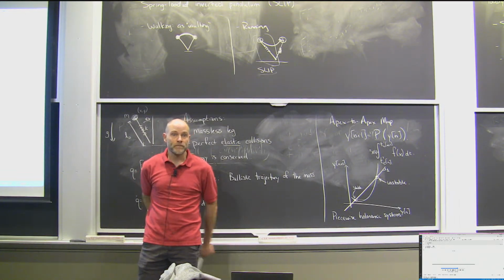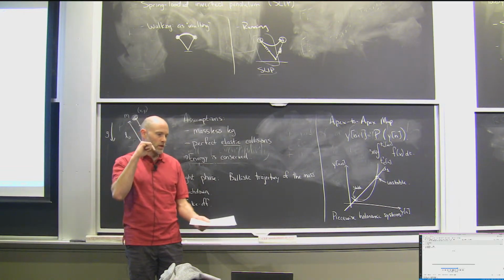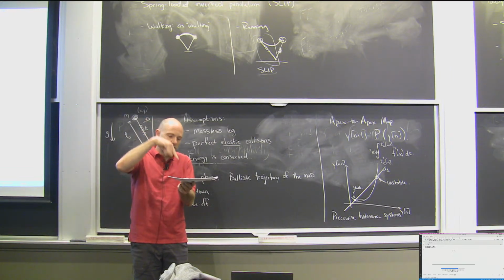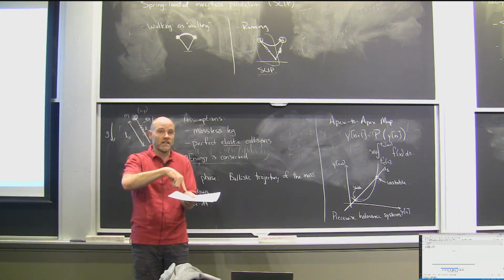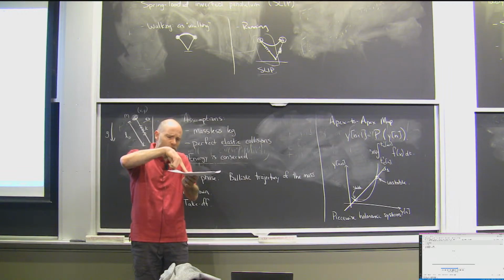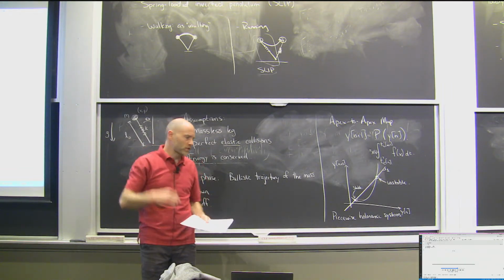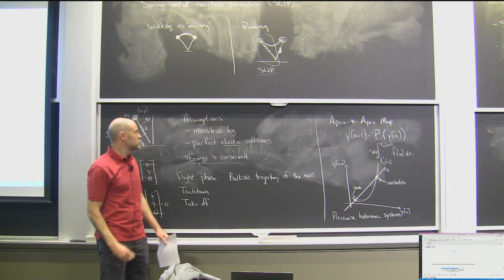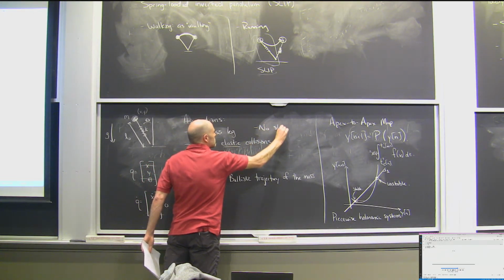Yeah, so here you're assuming that the leg is not slipping, right? Like it's always meeting the ground so that the spring is compressed, otherwise you wouldn't conserve energy. Correct. Let me repeat the question just for the cameras. Yes, we made assumptions about no slip, but the reason I didn't even say slip was because it instantaneously comes into contact, and then we make a pin joint. So there is a no slip assumption while I'm in the stance phase. That's correct. I basically make this into a pin joint. So there is a no slip assumption too. I should write that here. No slip. Good call.